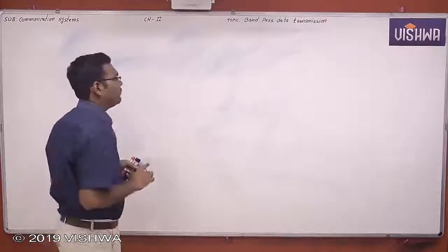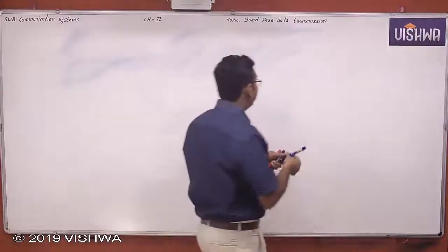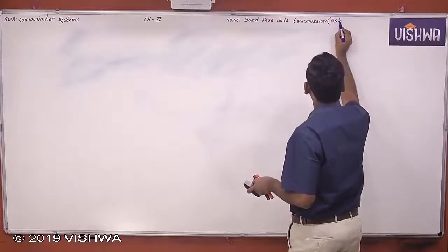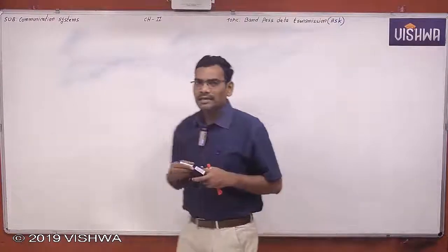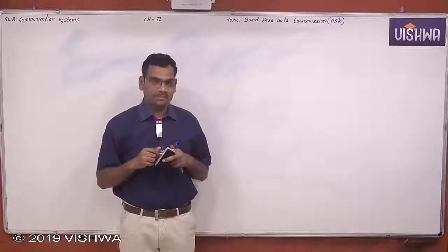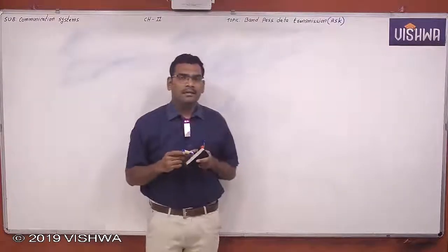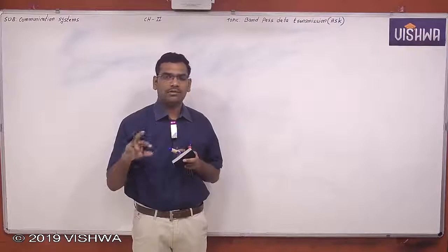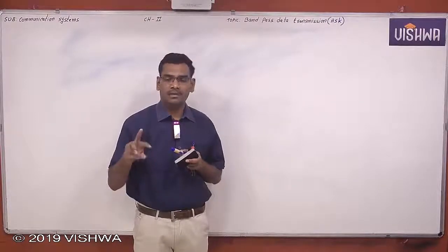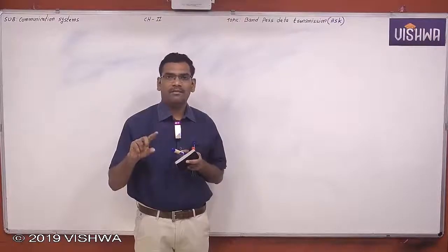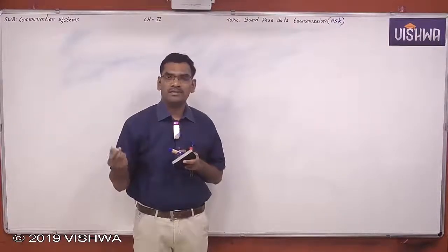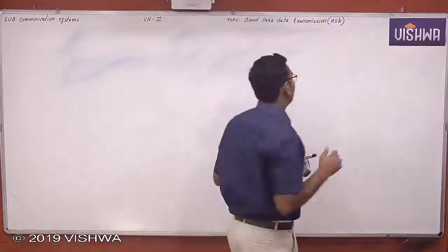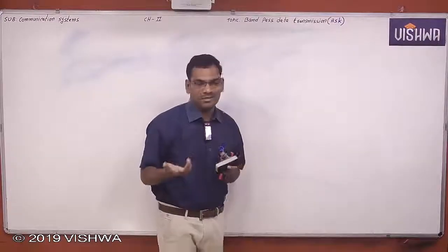Now, what is amplitude shift keying? First, you tell me. ASK. Amplitude shift keying. See, the word keying is nothing but sending. You can understand that easily. So he is transmitting ones and zeros, 1 0 1 0, only 1 and 0. So keying is nothing but sending for 1 and for 0. What it will be sending for 1 and what for 0, we will see. Keying is nothing but sending, or the process of sending ones and zeros is also called keying.